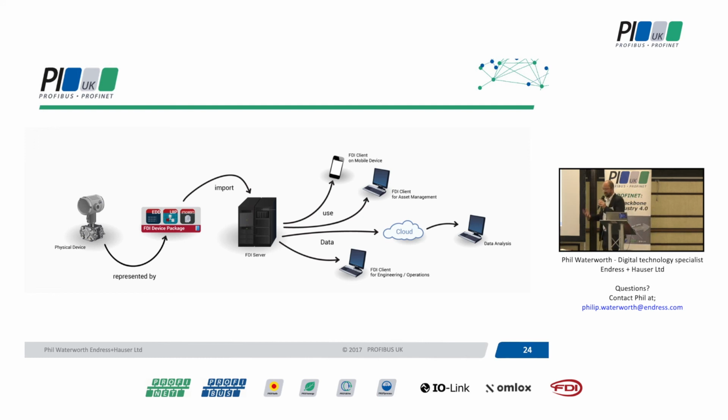So FDI tries to bring the benefits of EDDL and FDT together. Just one FDI package, which consists of an EDD, because they're much easier to write than FDT DTMs, some sort of user interface plugin and lots of the documentation all in one package. Written by the manufacturer, very easy to get hold of. Put it into your platform, and then you're able to get the configuration, diagnostics, and of course with various different FDI tooling, get that data sent to other places if required as well.